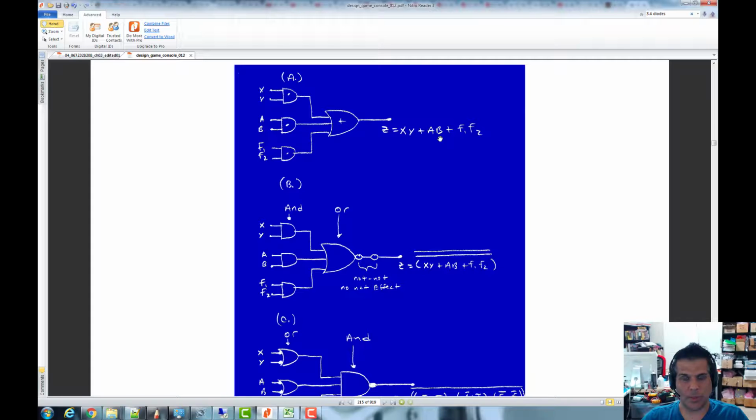Well, we can use DeMorgan's theorem on it. So here we go. So this is what we got. I'm going to add 2 bubbles to it, 2 inversions. The result is still going to be the same, right? So that doesn't do anything. But I kind of hold this one off over here, and then I process this one. So I push the bubble through the OR gate, so the OR turns into an AND. Then I get a bubble here, and a bubble here. All these get inverted, right?